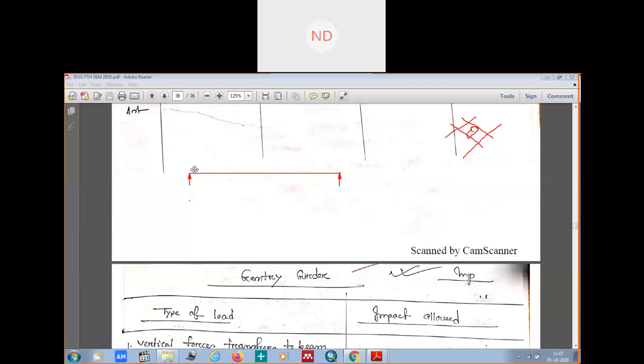Here, this is the crane girder, suppose, and this is the UDL, the load of the crane girder. These are the reactions. Now, where and how much is the maximum load going to be present? Somewhere here we will have W, the load, which is nothing but the hook plus your trolley. At this corner you will have your maximum loads. This is the position in the crane system where you have the maximum wheel load.